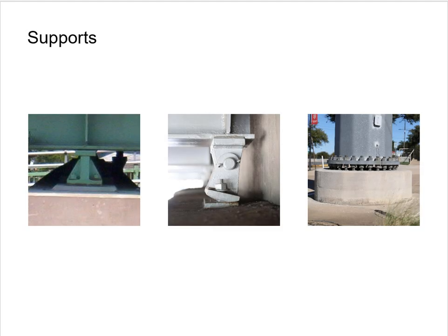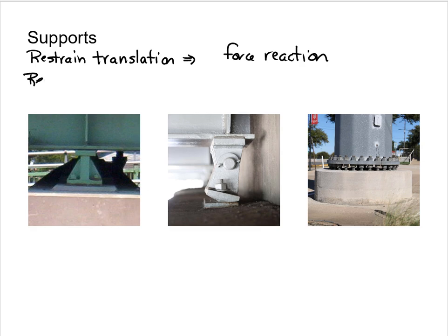To idealize supports, we consider which motions are restrained or prevented. If translation is restrained, a force reaction is generated in that direction. If rotation is restrained, a moment reaction is generated. Most supports fall into three idealizations.